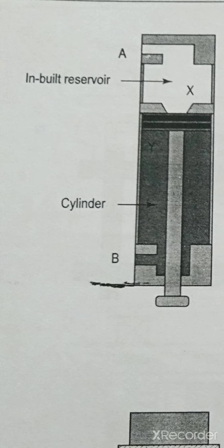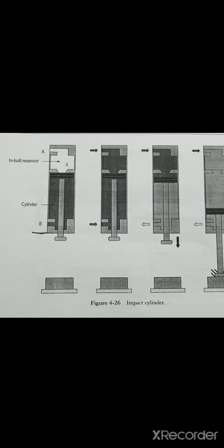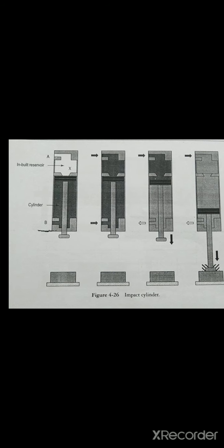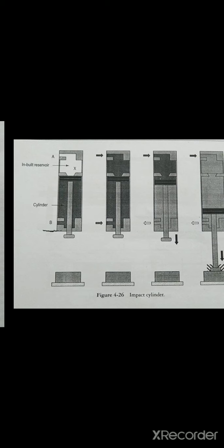An impact cylinder can be used as a power unit capable of providing the impact load to an infinite variety of press work applications, conveniently carried out on machinery such as fly presses, kick presses, drop stamps, crank presses, etc. In fact, many applications benefit from the impact working, as the high tool velocity and high rate of energy application can produce results such as cleaner edges when cutting and enhanced grain structure when forging. For all impact applications, complete guarding must be integrated, either fixed or interlocked with the control circuit.